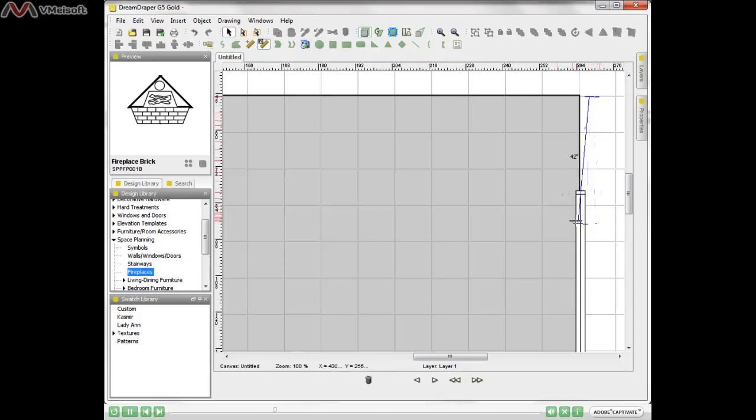If I want to have a perfectly straight line, depress the Shift key and keep it depressed as you're drawing, and there, it will lock into place. It is now perfectly up and down, and then you can release your mouse and also release your hand on the Shift key. By depressing the Shift key as you're drawing a dimension tool, you can have a perfectly straight line either vertically or horizontally, or even at a 45-degree angle.